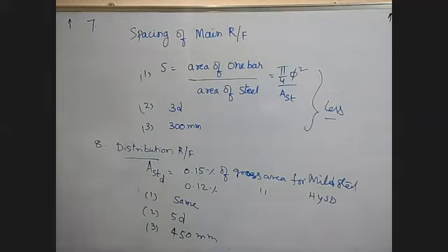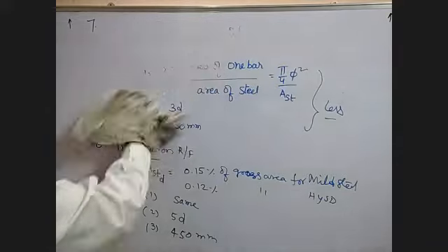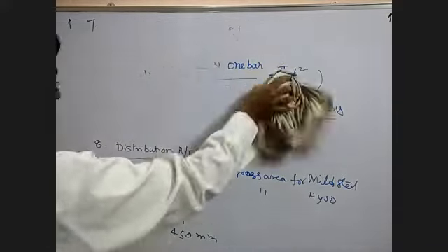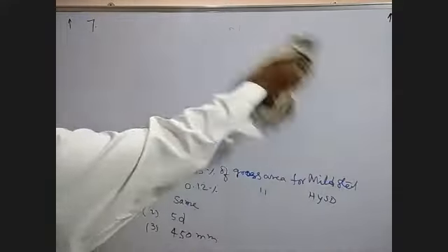Then you have the ninth step, the check for shear, deflection, and development length, same as you have done in the beams.